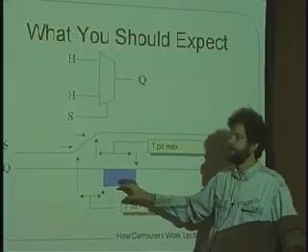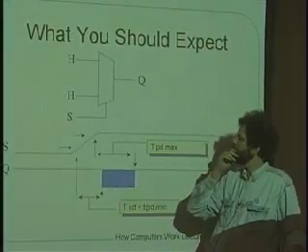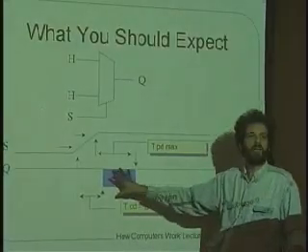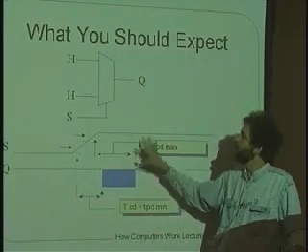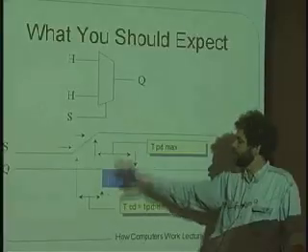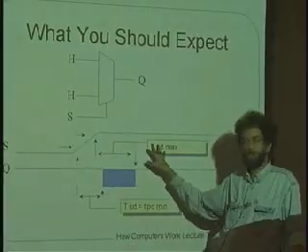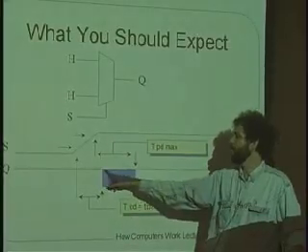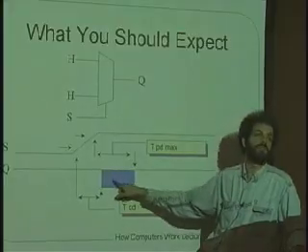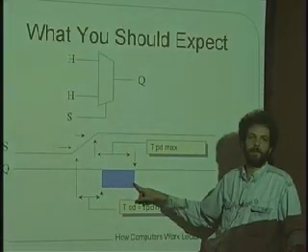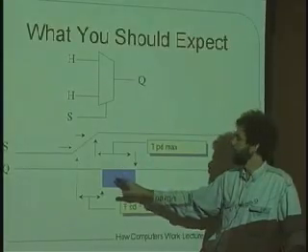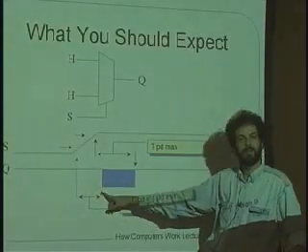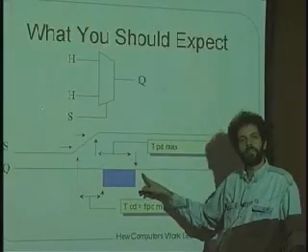Okay, so I thought it might help us understand. It turns out that you can figure out the time where the hazard might take place with this. If we were given the specifications for the device in terms of TCD and TPD, what that would say is if a hazard is going to take place, it'll happen somewhere during this blue time here. And so that's the meaning of the difference between when the TCD is up and when the TPD is up.